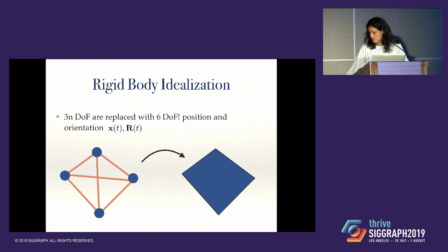So this makes sense if I think of this object as rigid. I have 3 numbers that describe where I'm placing it. And that's the three numbers in x. And now I have 3 more numbers that will describe how it's oriented. So imagine there's a surface of a sphere, and I'm pointing the top of my bottle to some point on the surface of the sphere. So that's 2 more numbers, because a sphere has latitude and longitude. And now I have a third left over, and this bottle wasn't the best example because it's rotationally symmetric, but the third one is rotating about its own axis. So if this bottle was not symmetric like that, then you would see that better. But that's my third one. So I have 6. In 2D, we only have 3.